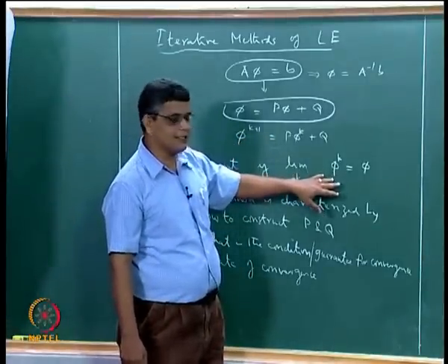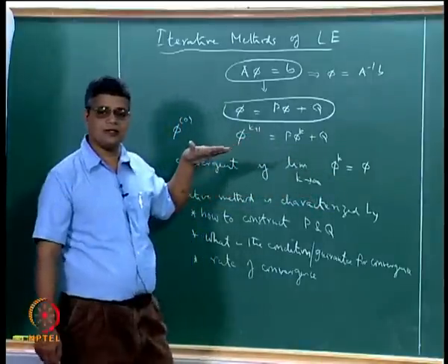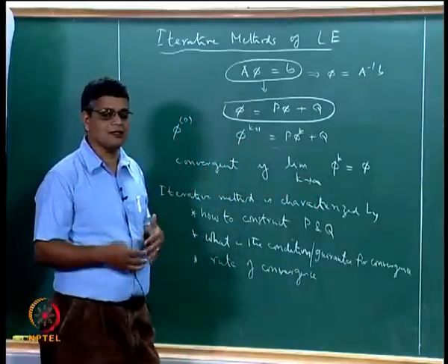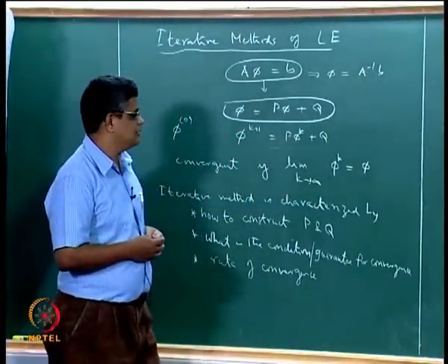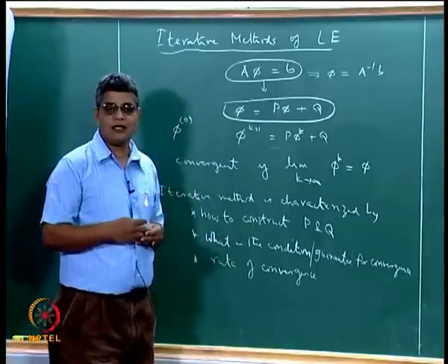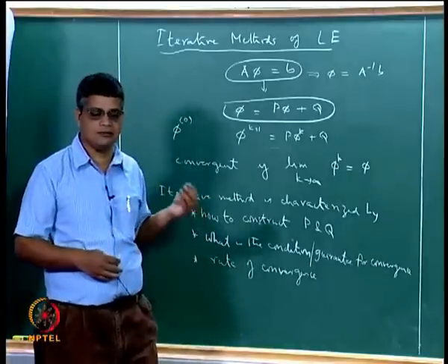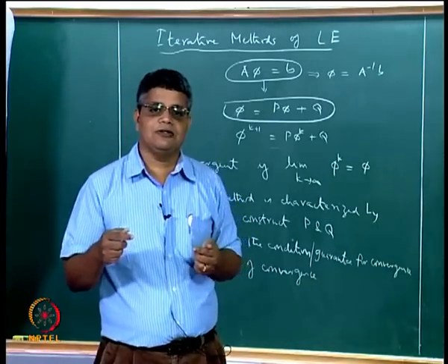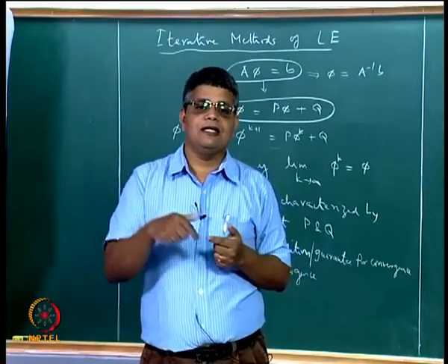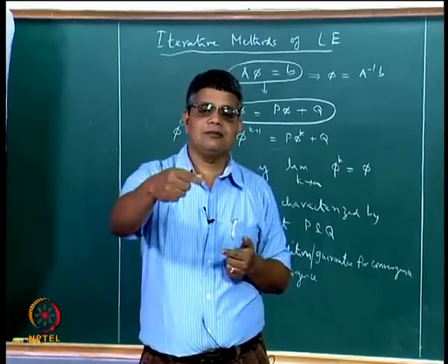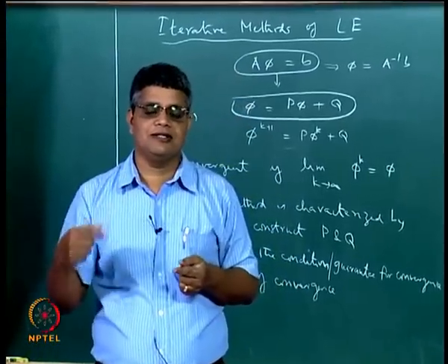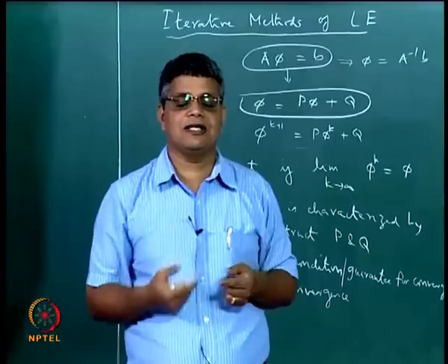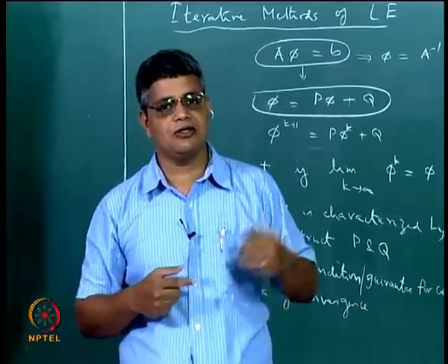In such a case, we can stop the iteration at any time. We already have some guesstimate values for phi, and this will be useful in the context of our CFD type of solution, where we take account of the coupling between the x momentum equation, y momentum equation, z momentum equation, and the pressure correction equation, or the continuity equation.